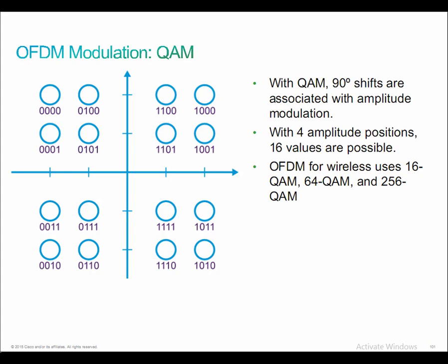So with this speed, only 1/2 of the bits are information bits, and the rest are redundant. We want to make sure that if there is interference, we can still understand the signal itself. By increasing the density of the useful information to 3/4, like we talked about before, now we have 750 kilobits per tone times 48, which gives us 36 megabits per second of throughput.